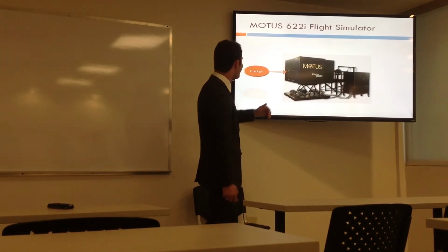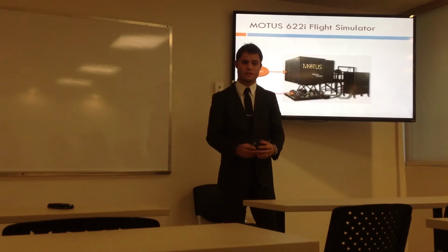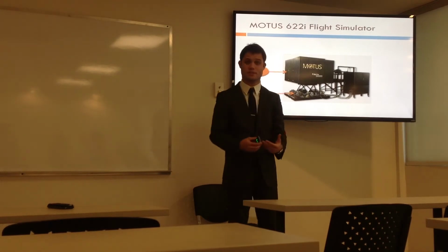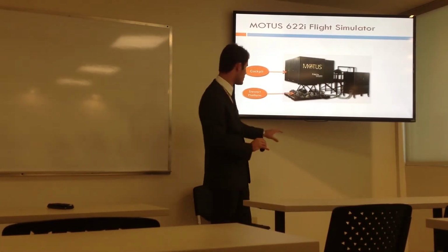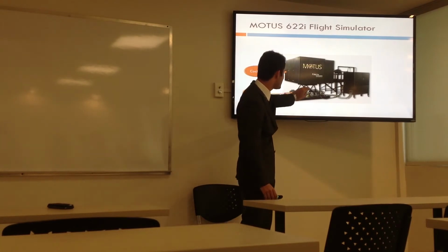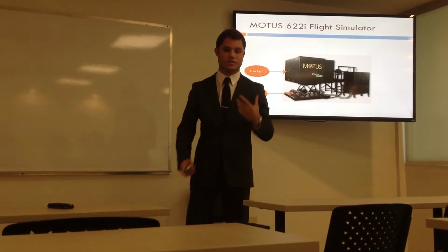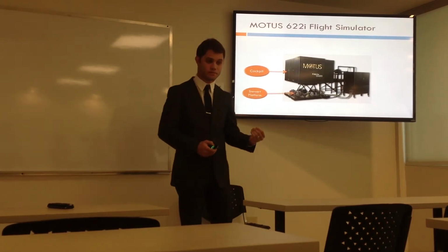Okay. Afterwards, we have what's called the Stewart platform. This is a special type of platform that's used in these situations, and it also has a lot of other applications in the automotive and aerospace industry. But right now, what I want to focus on is it gives you the illusion that you are moving within the 6 degrees of freedom using a technique called acceleration onset cueing.